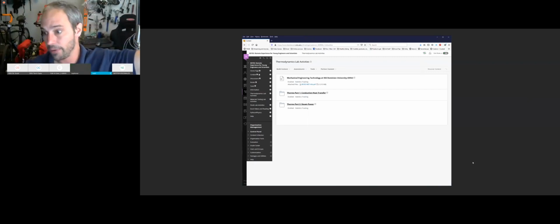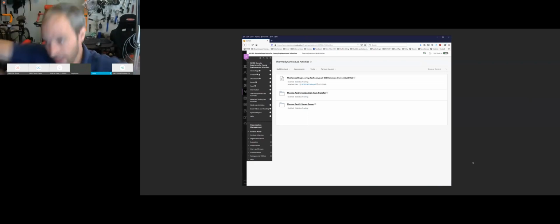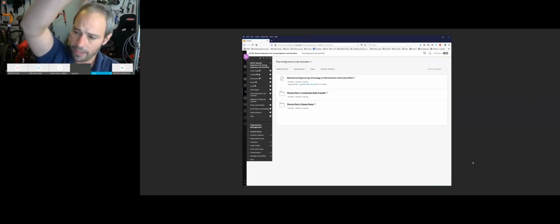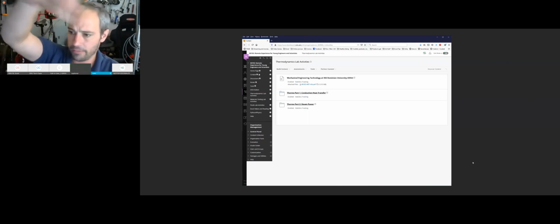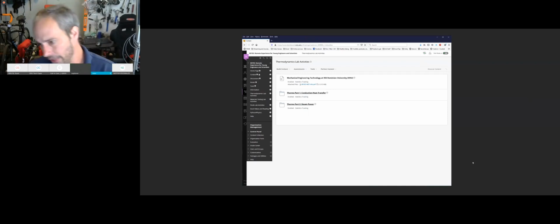Now the problem is you're still at a very, very high pressure and you're at a higher temperature than the evaporator inlet. So what you do is you expand it through a thermal expansion valve, which is basically an orifice. You can think of it as a pipe with a disc in there, a little hole. It goes there, it sprays, and it suddenly drops its pressure. And the Joule-Thomson effect, if you Google that, tells you that when you drop the pressure drastically, you also drop the temperature. So we get it back from the 120 degrees Fahrenheit, or it's probably not quite that hot now, but whatever temperature it is, down to the 20 degrees Fahrenheit again, and it continues the cycle.